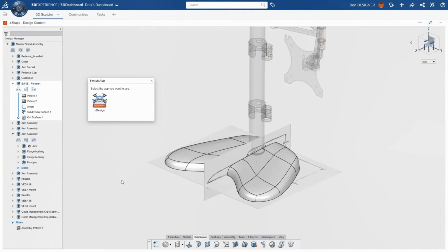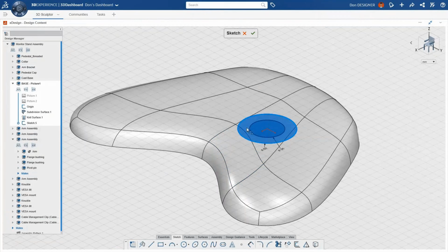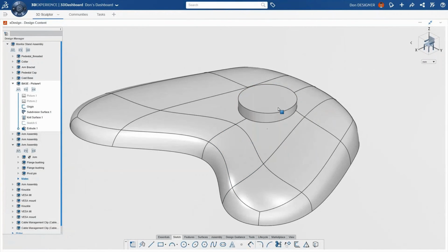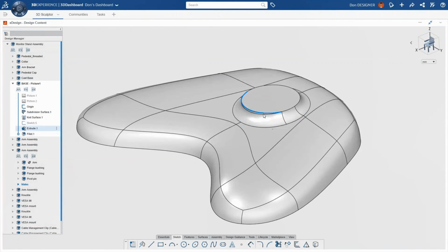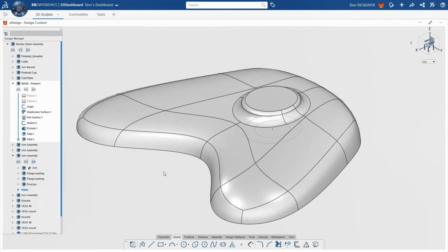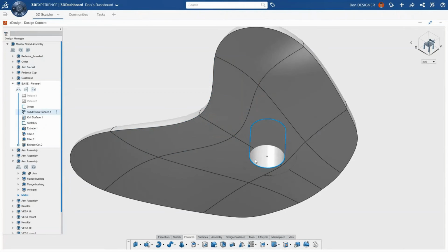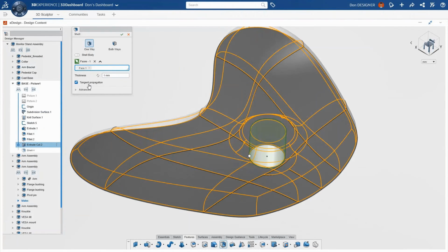What he's going to do is add some more of the detailed design to the shape. So he's going to switch back to xDesign, which gives him access to some of the more detailed modeling capabilities outside of the conceptual tools he was just using. Don's going to start to design the mounting boss that's going in the center. Of course, it needs to be mounted to the central part of the stand. So he's going to use some regular extrudes, add some fillets to blend it in to the body. And then finally, it's going to be a molding, of course.